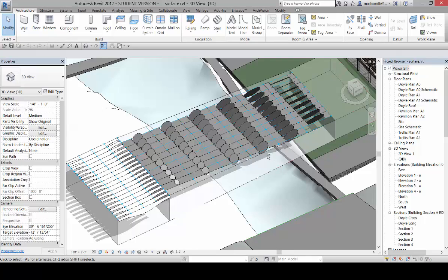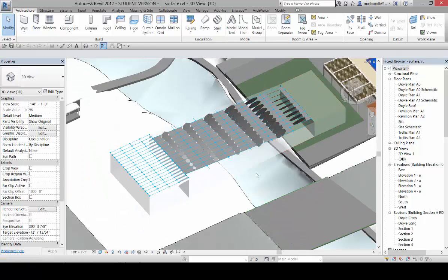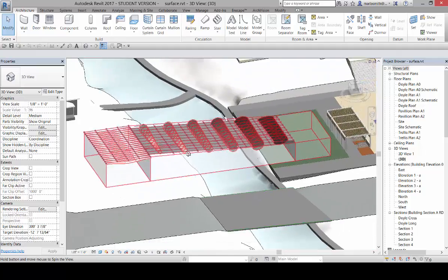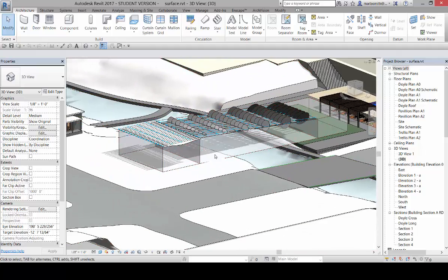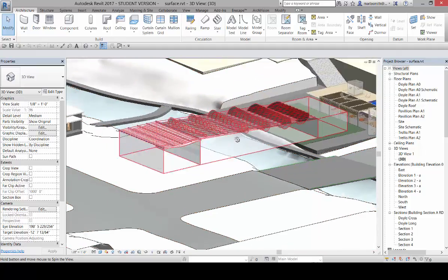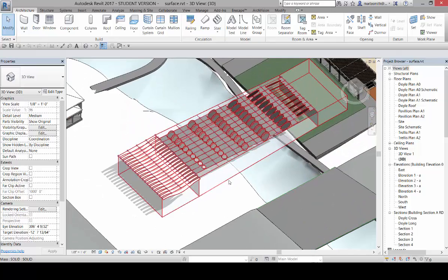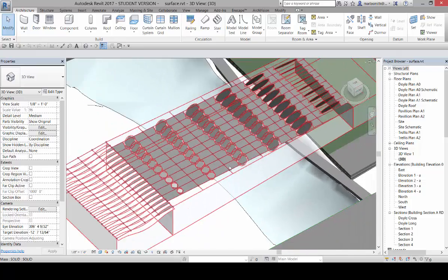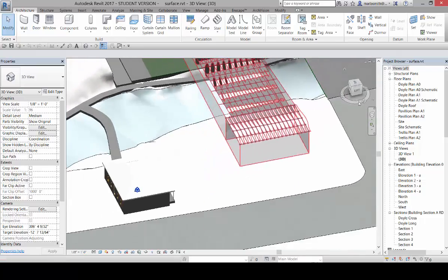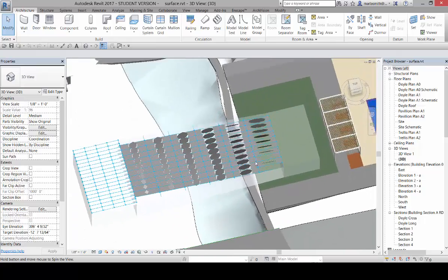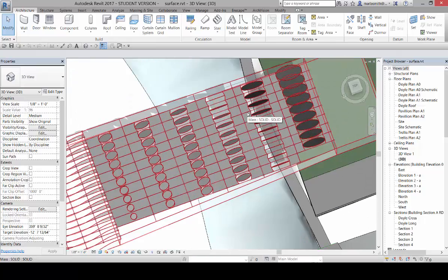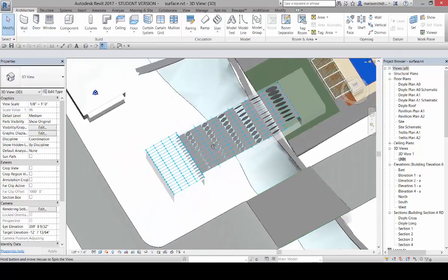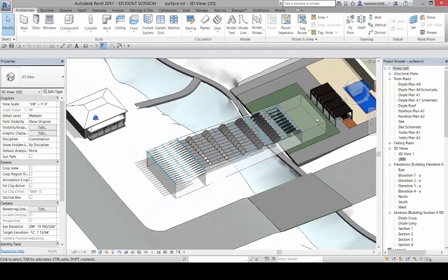Alright, so for this one we are going to work on surfaces. What I basically have here is a mass made of surfaces, and I've used those surfaces to create a divided roof, and I've placed some louvers on this divided surface, and then I've placed an attractor with a rotated sort of circle piece on these guys. And so we're going to start from scratch to create this.